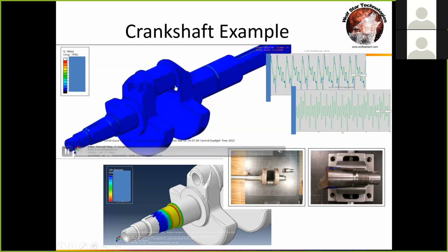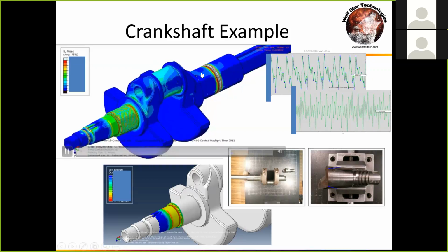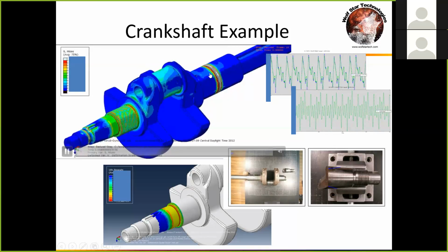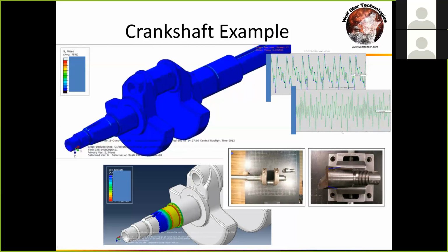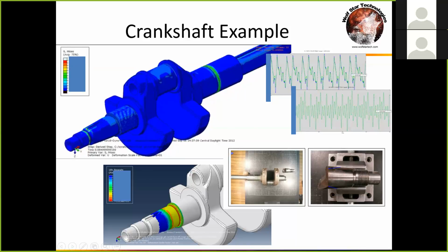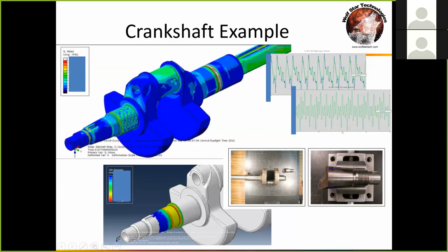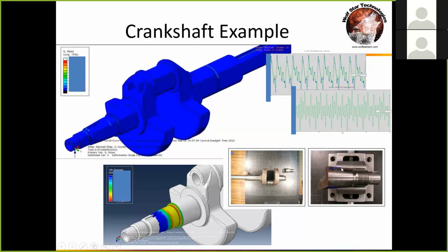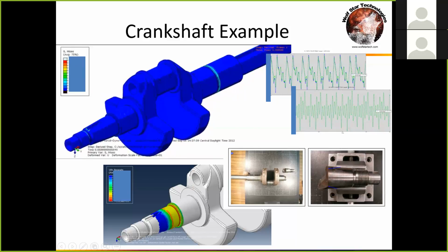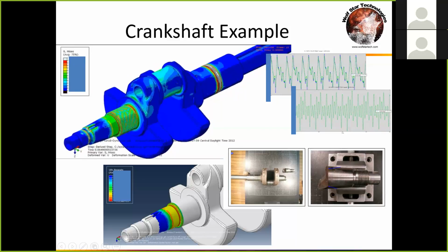When I reviewed the crank pin loads with the engineers, they thought the loads I was calculating were appropriate for the speeds the engine was running. So we had a sense check that we were calculating things right. We ran it all through FE Safe, and FE Safe identified this little area out here on the end of the crankshaft as being the area of maximum damage, which correlated exactly with where it was occurring on the real part. So really nice example of getting it right.